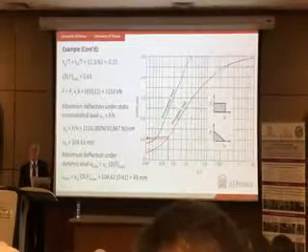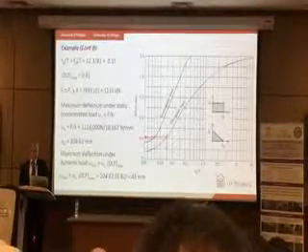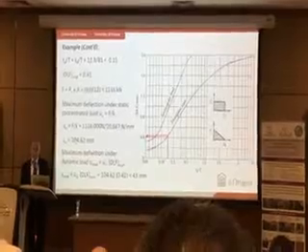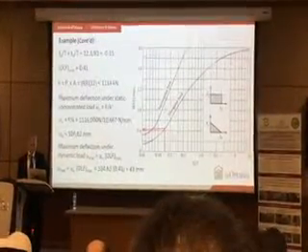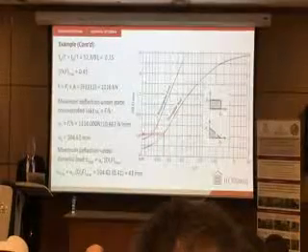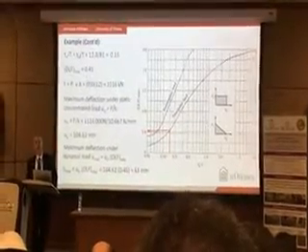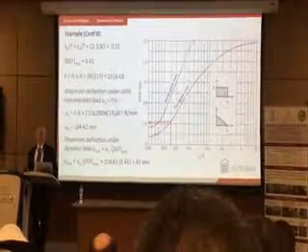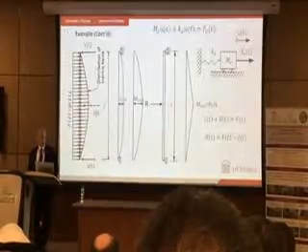That factor is multiplied by the static deflection. Static deflection in this case is 104, as you can see, simply found from force divided by stiffness. This is static force divided by stiffness. And then I multiply it by the dynamic load factor. I get 43 millimeters, giving me the deflection under dynamic load. You see, just like that, I did dynamic analysis. Once you have these charts, life becomes very easy.